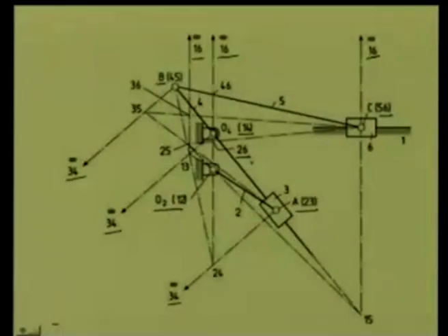That means, for this configuration, if one prescribes the input angular velocity omega 2, which is given, we have to determine what is the velocity of the cutting tool, that is link number 6. What is the velocity of link 6 or velocity of the point C, which is same as the sliding velocity of the cutting tool.